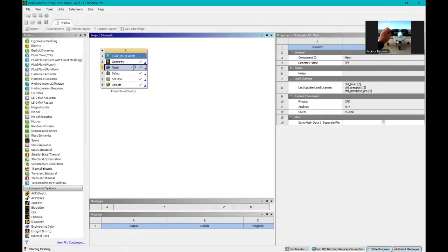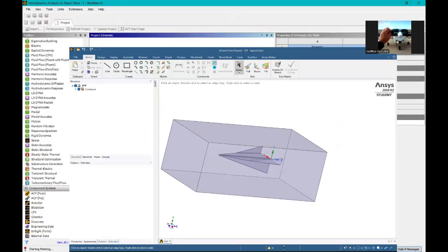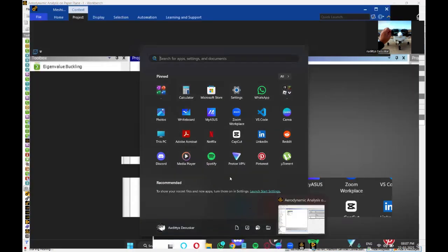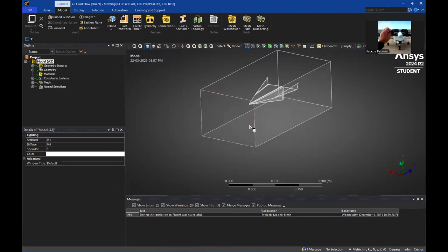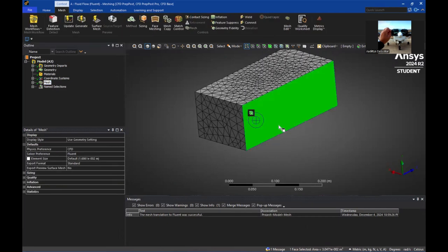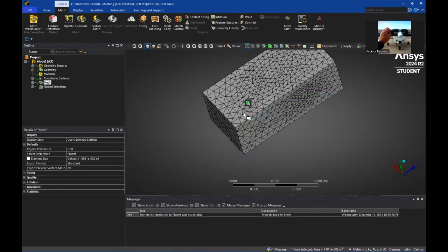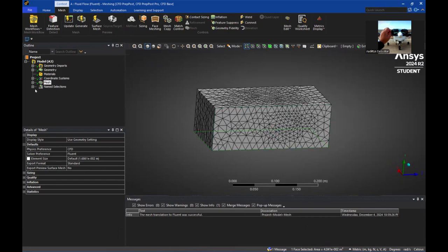Now, coming on to the mesh, I would like to show you the mesh. Now, you have seen the computer geometry. Now, we meshed it for obvious reasons, so that the computer can analyze and solve the governing equations in it. So this is the ANSYS meshing module, and this is the geometry that we imported, and this is the ANSYS mesh. You cannot actually see the insides here because every part of the geometry is meshed, but I could show you using the name selection.